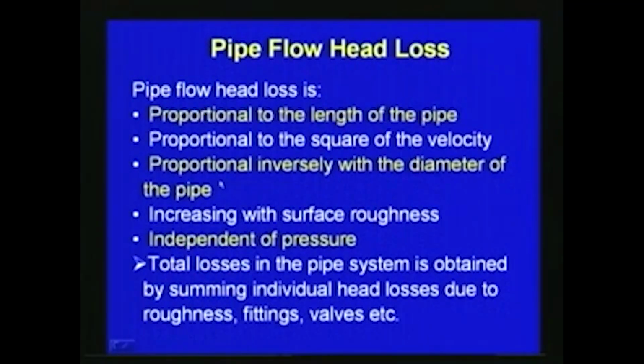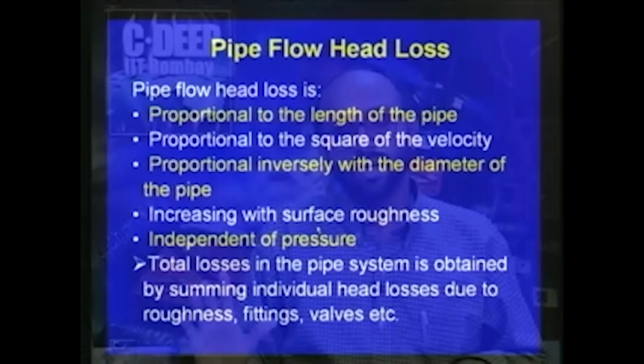But with respect to this relationship, you can see that this pipe flow head loss is independent of the pressure. It is mainly depending upon the velocity, length, diameter, and also the roughness. It is independent of the pressure.